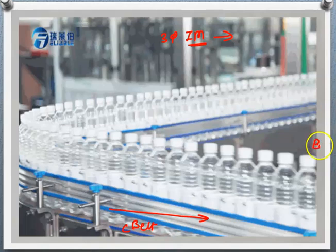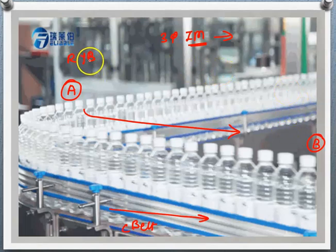Suppose at this position B, it is filled and capped. And the direction of the conveyor belt is like this when the normal phase sequence is applied. When RYB is applied, the direction of the induction motor is such that the conveyor belt will move from this position A to position B.